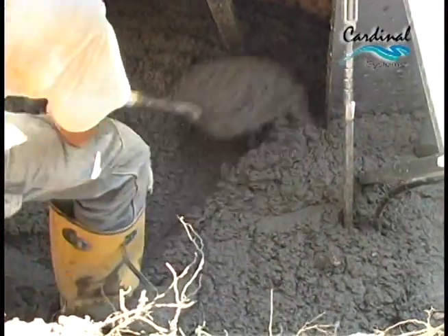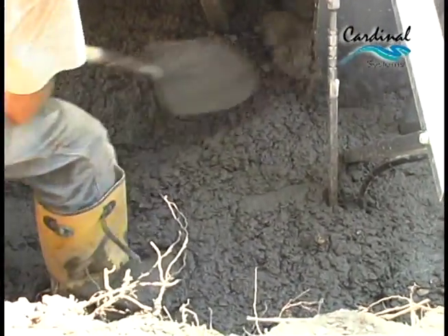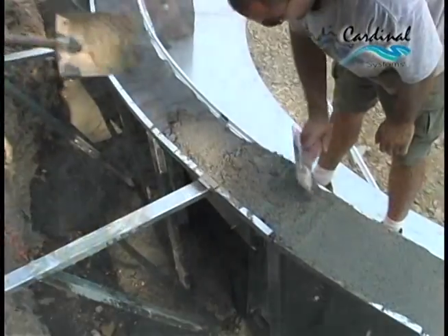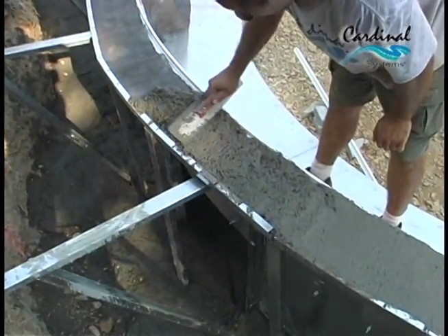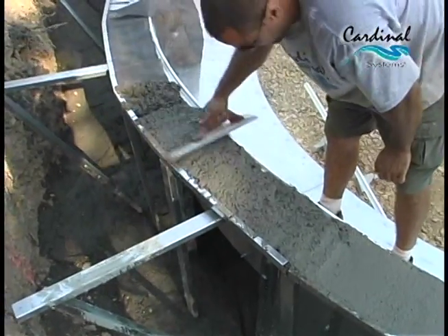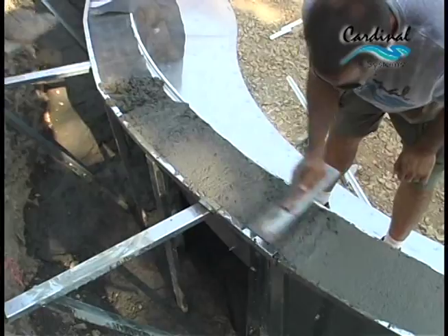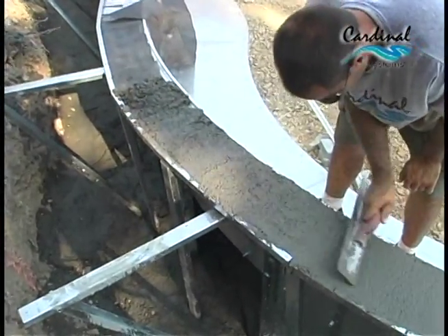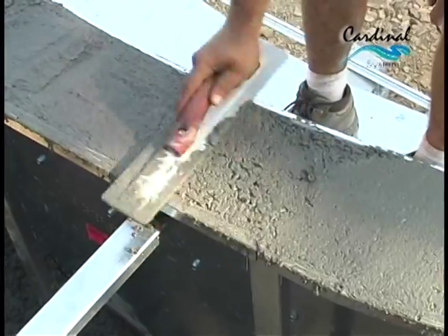Here, the installer is shoveling material under the sun deck so that the entire perimeter of the pool has an appropriate collar. Once the collar has been poured, use pea gravel mixture to mud in the base of the stone coping support system. Use a trowel to work the mix to a level plane, working out air pockets and high spots and making the surface as smooth as possible.